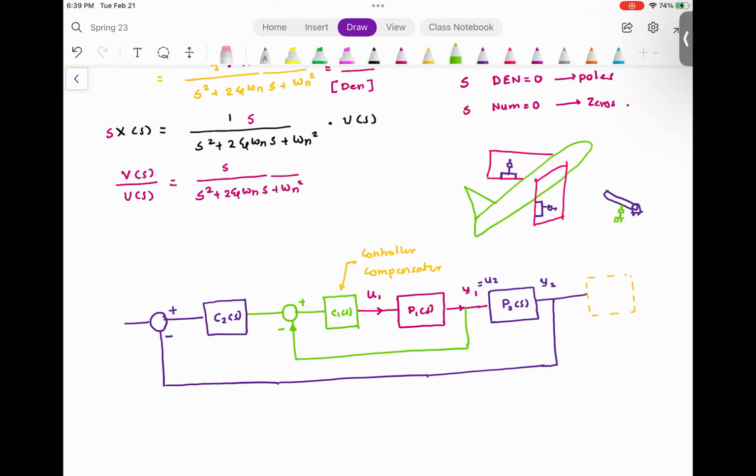It may happen that even though you are increasing the input, the actuator will not move beyond a certain location. Think about it like you floor your gas pedal. You want the vehicle to go even faster, but the gas pedal is physically floored. It cannot turn anymore. That would happen with the actuator.